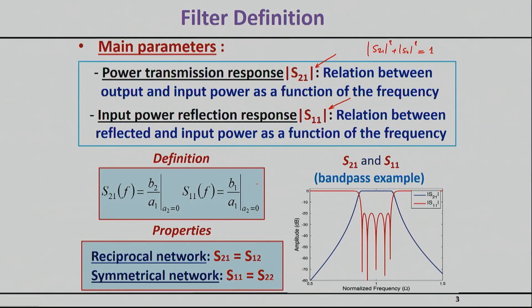In lossy scenarios, the situation changes quite a bit. So for example, if you look into a bandpass case, like the one that you can see here, there are going to be some reflection zeros, which you can basically see here. These are essentially the frequencies where your S11 is identical, equal to 0, in which case your S21 should be identical, equal to 1. And then there are going to be other frequencies where your S11 is simply below a threshold. In this case, it's 20 dB, and that means that your S21 must be above a threshold, must satisfy an insertion loss requirement.